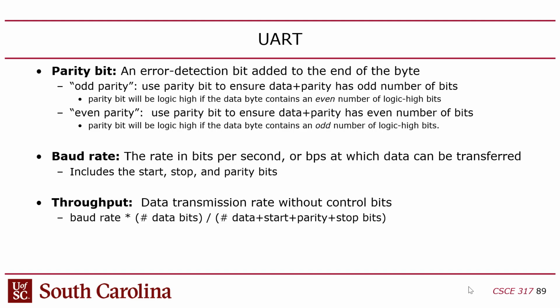So if you have an Arduino chip, for instance, you might be able to find out by reading in there. But even then you might not know, because the Arduino chip supports multiple baud rates, and you don't necessarily know what the software set it up to run at. So sometimes you literally just have to guess. But it can be challenging because the baud rate's only one of the things you have to guess. You also have to guess the number of parity bits, the number of start bits, and the number of stop bits.